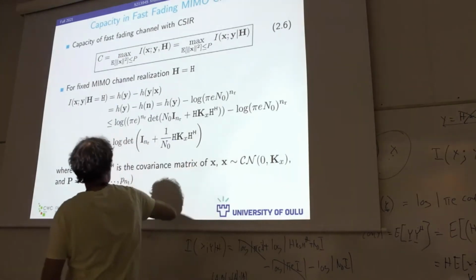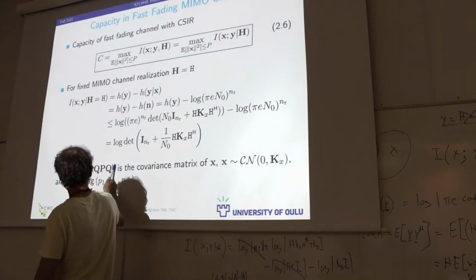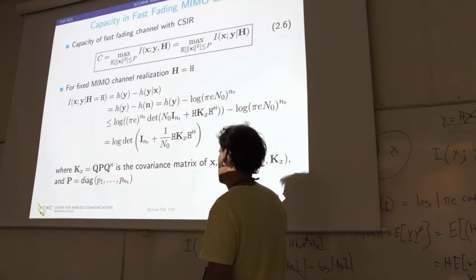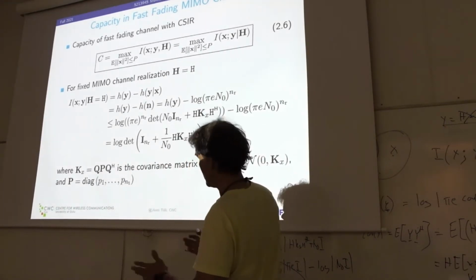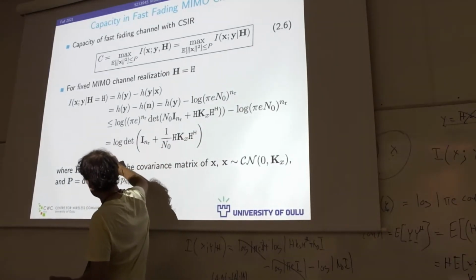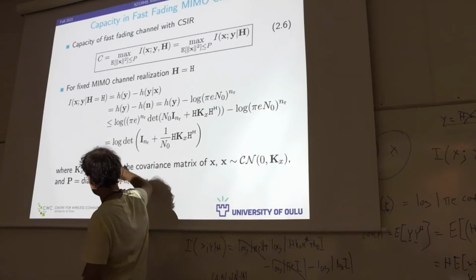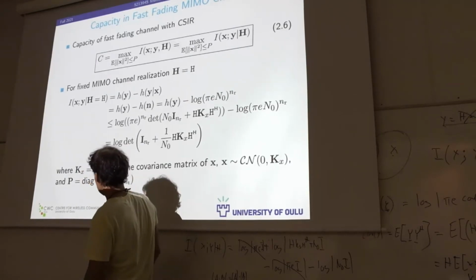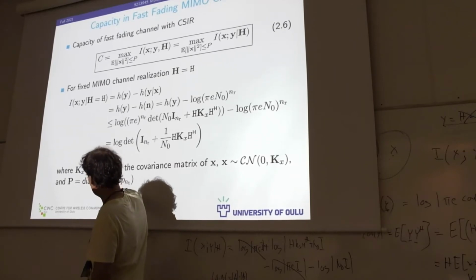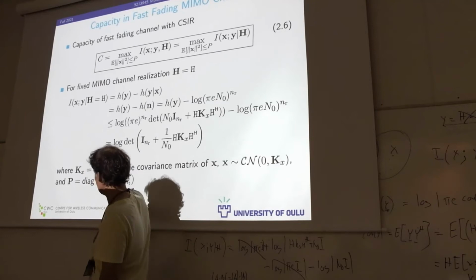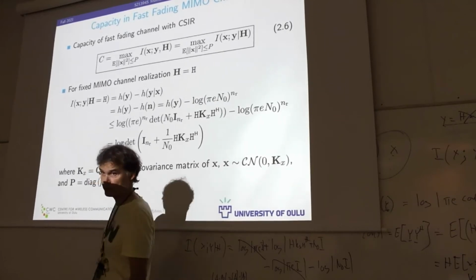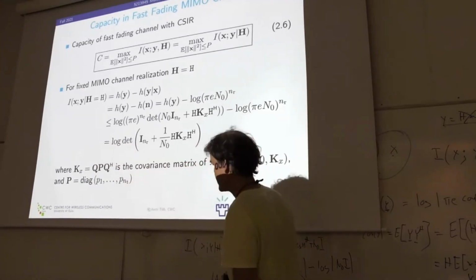Okay, the covariance matrix is a Hermitian matrix, so we can of course split that using eigenvalue decomposition. For example, using eigenvalue decomposition, we can split the Hermitian covariance matrix into normalized precoding vectors or matrices, and then a power loading matrix. This is something that we will cover.